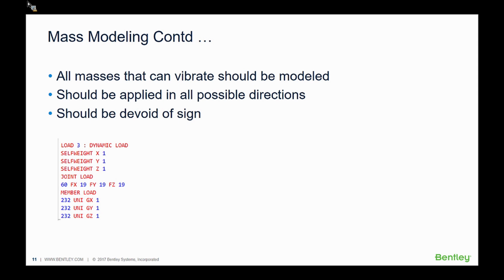So to model all the items that we discussed in our previous slides, we can use a combination of self-weight load, nodal load, member load, floor load, etc. The software then internally converts these loads to masses by dividing them by the acceleration due to gravity.